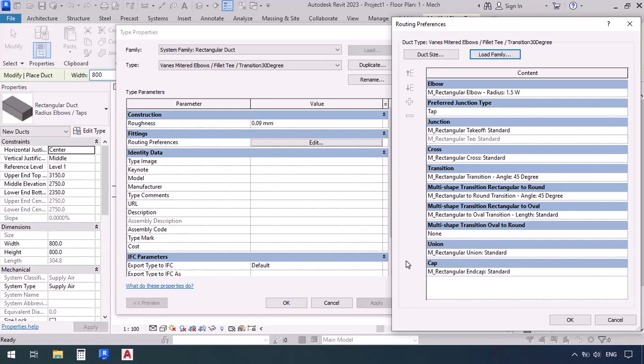But in a whole project, little by little, when architectural, mechanical, and other items are added, the size of your file would become so big that it makes it hard to work with. So make sure which families you're loading. Don't just spontaneously add too many families. It's almost like when I go to a hypermarket and only pick up the things that I really need and then go to the cashier.